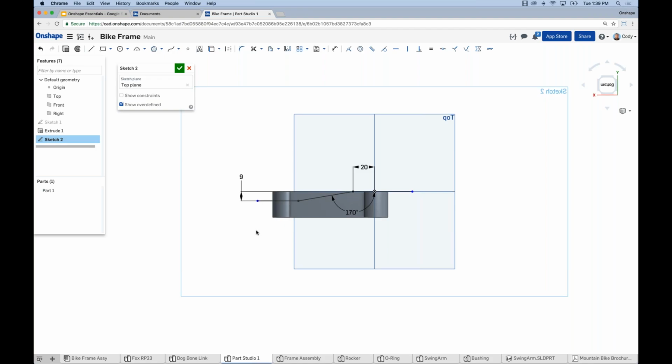So now that I have these lines sketched, I want to offset all 3 of them at once. So I'll select the offset command, and I'll left-click drag one of the lines. It will automatically grab everything in that chain of lines. Enter a value of 8 for our offset, and now we have an offset of 8 millimeters for those 3 lines. So offsetting your geometry is really simple. Even if you have a lot of geometry that you want to offset at once, it's just a matter of left click dragging one piece of it and it grabs everything.